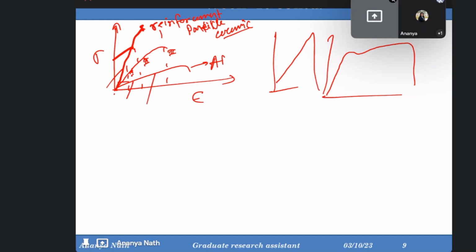So that's one problem. And related to these things, the rule of mixture will not always match with the real experimental value. So it's always recommended that you do not go up to the critical value, you stay far below the critical value, otherwise your composite will fail early.